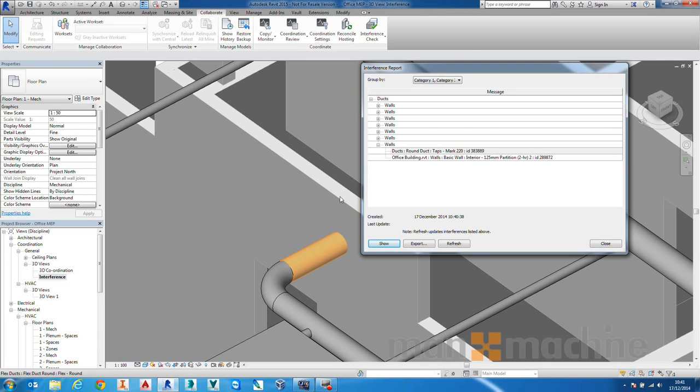And just bear in mind that because we're working inside of Revit, if we wanted to, we could take this wall, very quickly edit the profile and add a cut for that pipe. Because we've done that inside of that drawing, it would update the architectural model and they would get the notification and update changes of that.